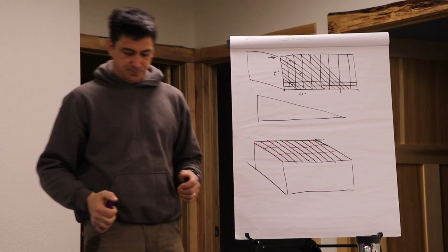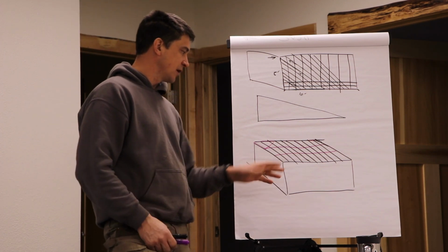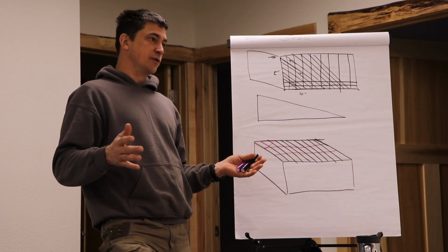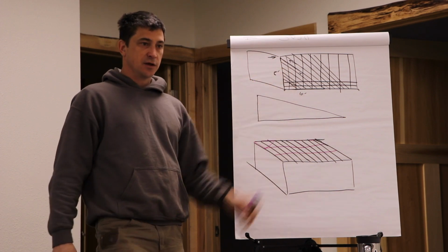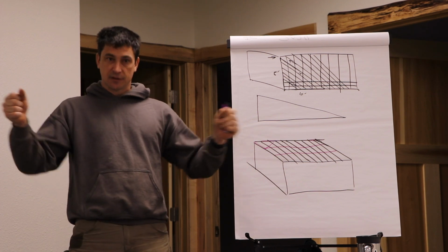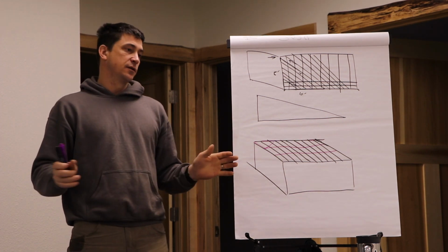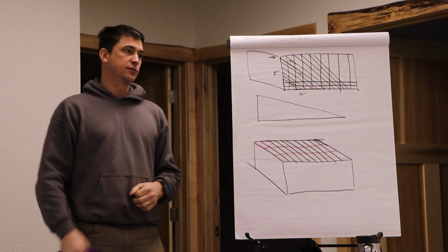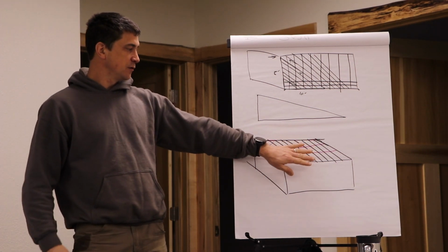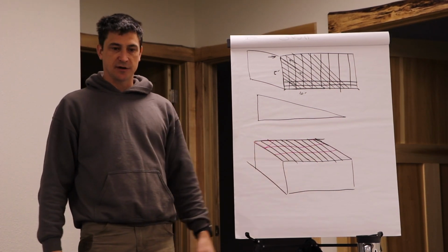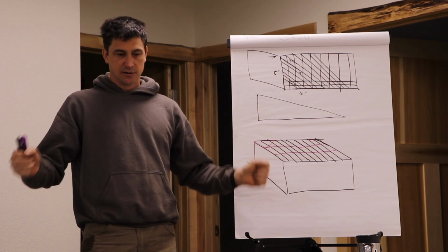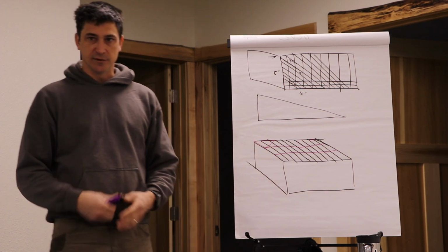And so when you get the opportunity to work on framing a new house, it's absolutely incredible. You can have your walls all braced, you can walk on them, you can be up there and they'll be really stiff, but they'll still wobble in the middle, and if you bang on something or drop heavy lumber, you'll feel the thing shake. You frame your second floor, you cap those walls and you put sheathing on there, and it just locks that building together so tight and so strong that it stops wobbling and shaking and moving.